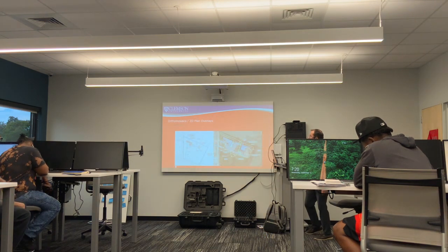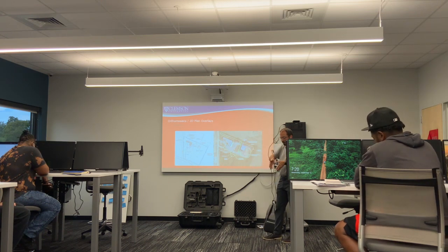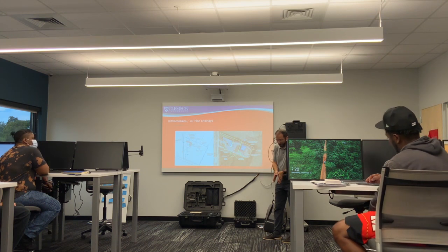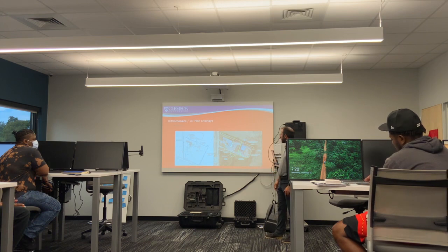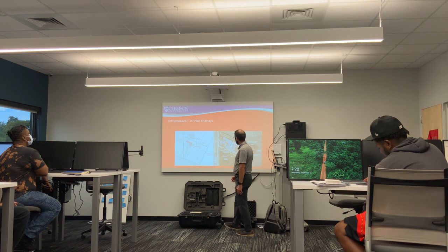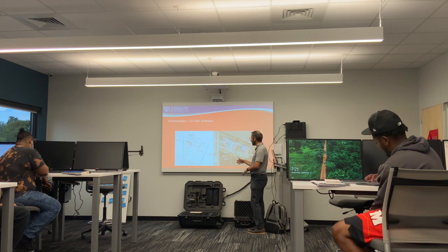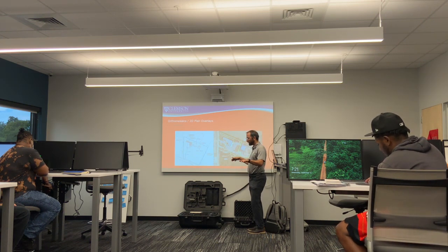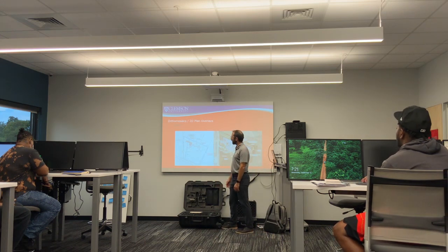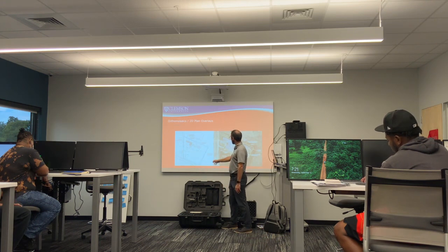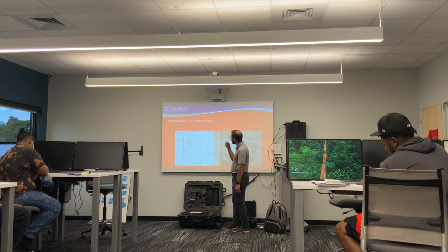So the orthomosaic is similar, but from that mesh, when you take a photo from above, you get that perspective view. An orthomosaic is kind of like Google Earth, but even in Google Earth you'll see the sides of buildings as you pan and tilt. Orthomosaics just stitch all those images together and you get a true top-down view, just like you would see in a construction drawing or a site work drawing like this. So this is essentially the site work drawing. I think this isn't on Clemson's campus.